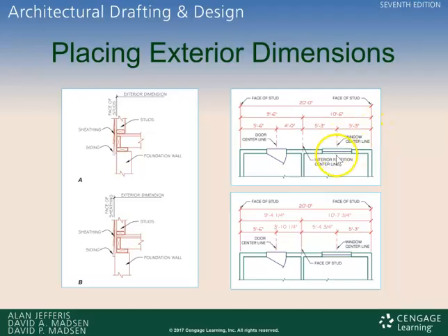And so once it's in place, it's harder to change. But the thing that is consistent would be the center line. So if this is a rough opening, you'll place your window within here when you're in the field, and then you'll be good to go knowing where to place it. Here is another example doing the same thing with the door center line, face of stud, and that's reflected over here in our elevation, which we'll get to in a little bit, where we're going to keep it with the face of the stud here.